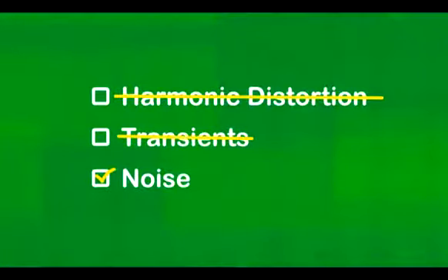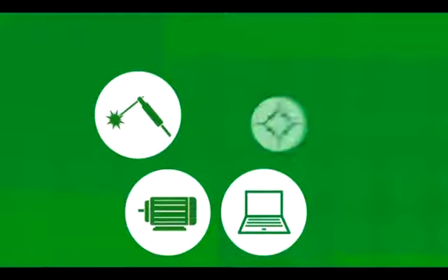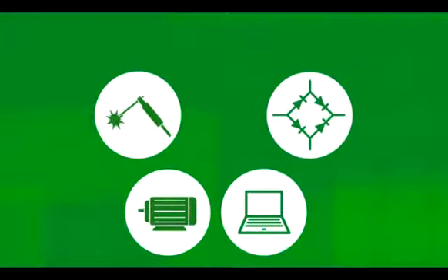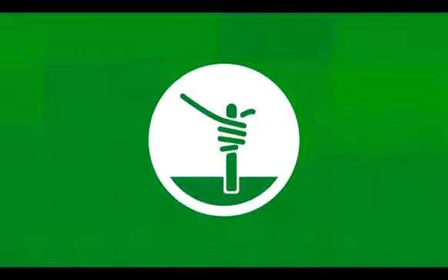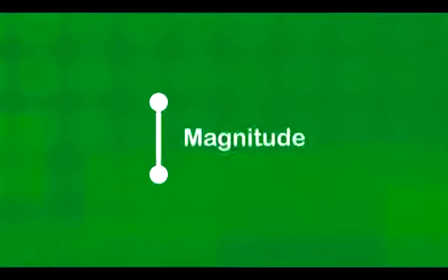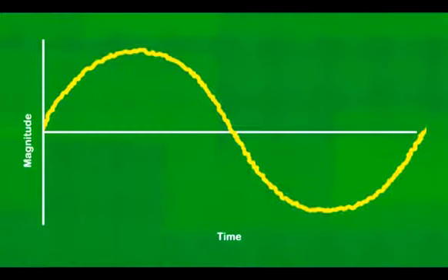There are a number of loads that can produce noise, including power electronic devices, control circuits, arcing equipment, loads with solid-state rectifiers, and switching power supplies. Improper grounding can often exacerbate noise issues. Typical magnitude of noise is less than 1% of the fundamental voltage signal's magnitude. While noise can disrupt the operation of electronic devices, it is possible to mitigate noise issues with various filtering techniques.